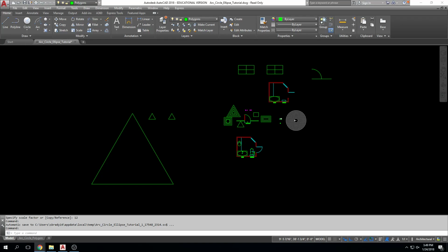Now, another thing that plays into that, so pen weights determine importance, but they're also determined somewhat by how a floor plan is cut, right? When you're looking at a floor plan, it is as if you had taken the building and cut it horizontally and pulled the top off and you're looking down into it, right? So you see the walls, the doors, the windows, the floor finishes, the furniture, you see the path out to the hallway, the stairs, the elevators, the bathrooms, all that stuff.